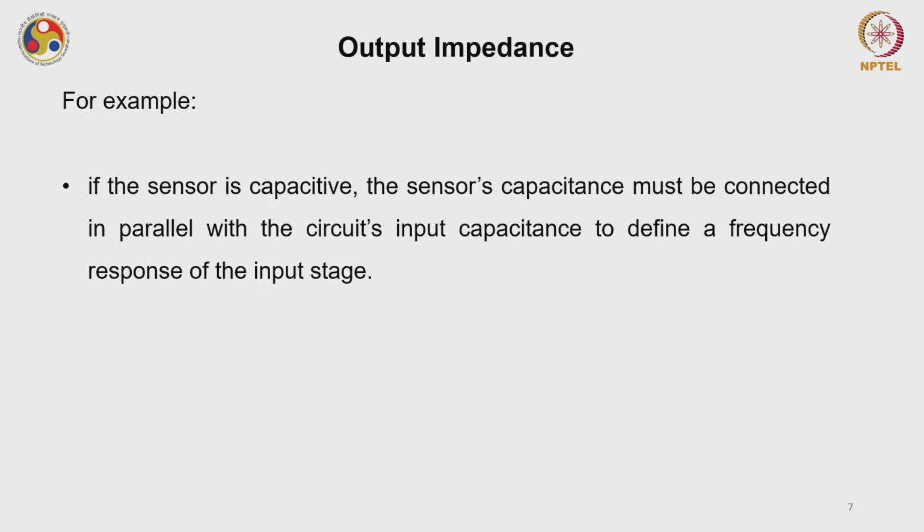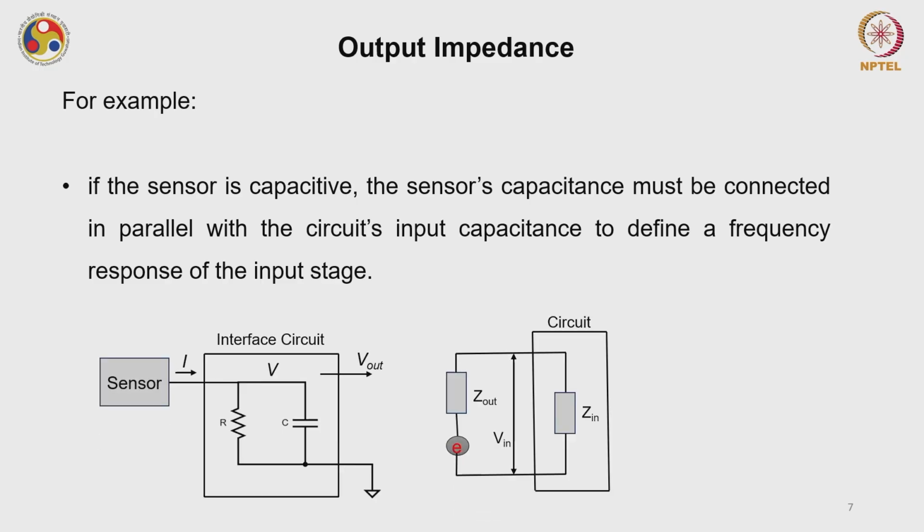Say if the sensor is capacitive, the sensor's capacitance must be connected in parallel with the circuit's input capacitance. This will help in defining the frequency response, particularly at the input stage of the device. Something like this I am talking about.